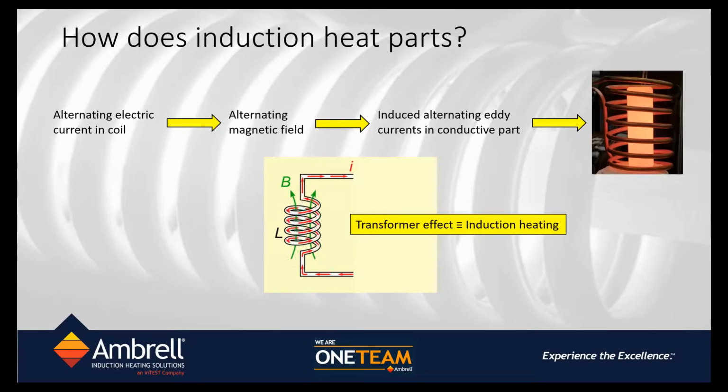The alternating current produces a magnetic field that also changes direction every time the current changes direction in the coil. This change in magnetic field interacts with the metal part and produces eddy currents inside the part. Now, when you have currents that flow inside a part, they tend to produce heat. This is the heat that is seen in the part.